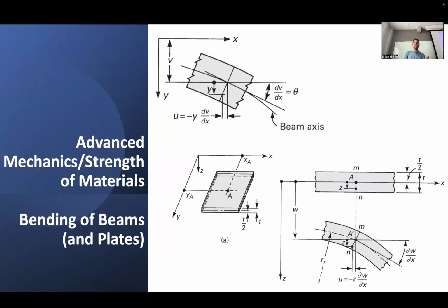In those situations, if you tried to use these three-dimensional volume-filling elements or solid elements to discretize those structures, then you'd need a heck of a lot of them in order to be able to get a good quality mesh where all the elements have a nice aspect ratio.